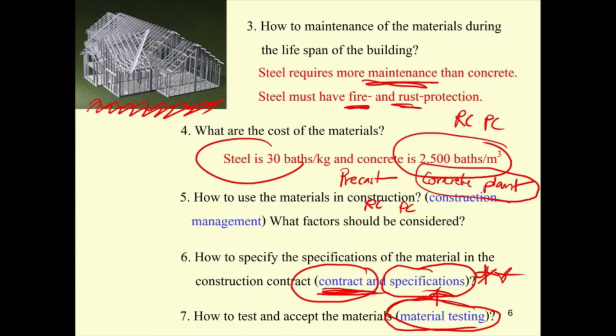That 10 tons of steel costs 300,000 baht. That's quite a lot of money, right? So when you buy things, you have to test for acceptance quality control. That means you are going to use the knowledge of this equation. Actually, most of the time you don't test it yourself, but when you get the result from the lab, you can compare it with the spec, and then decide whether you should accept the material or not.